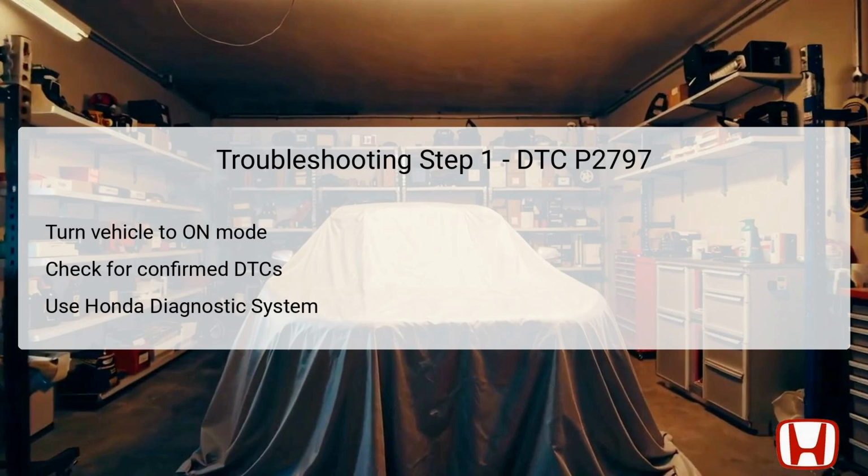The HDS is an essential tool for diagnosing various components of the vehicle, providing detailed information on diagnostic trouble codes. Confirming if DTC P0A94, a related code, is indicated is vital at this stage, as it may guide the technician to another area for further investigation. If the P0A94 DTC is not present, the technician will proceed to the next verification step.